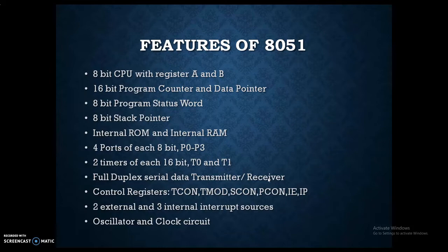And the control registers: timer control register, TCON; TMOD is timer mode register to select the modes of the timer; serial control register, that is SCON; power control register, that is PCON; interrupt enable IE, and interrupt priority setting register IP. And it has two external and three internal interrupt sources, and oscillator and clock circuit.